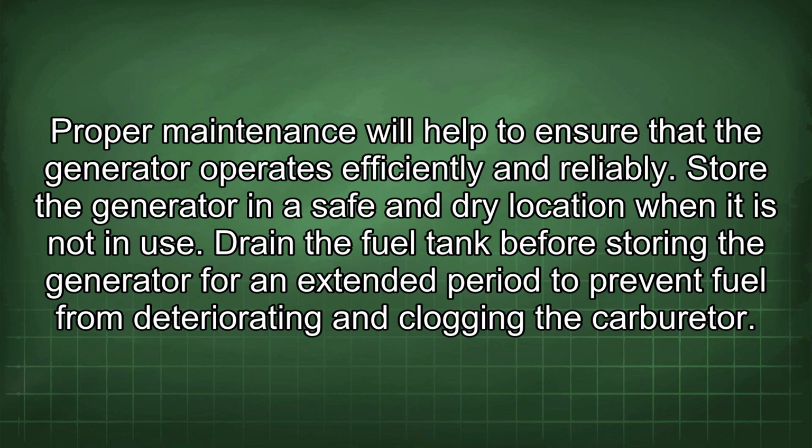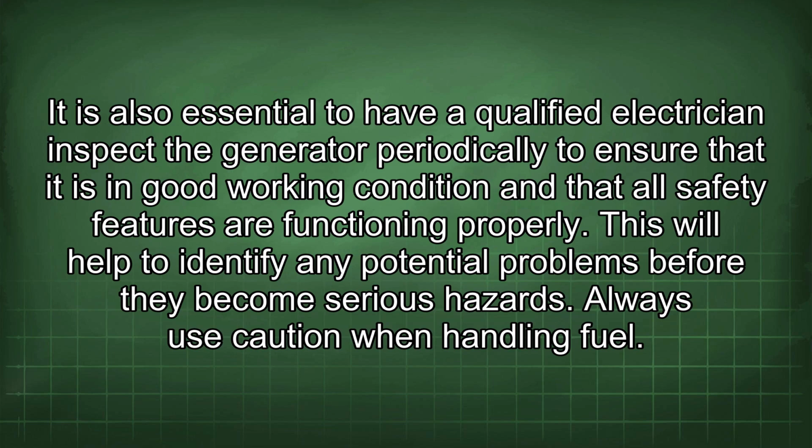Drain the fuel tank before storing the generator for an extended period to prevent fuel from deteriorating and clogging the carburetor. It is also essential to have a qualified electrician inspect the generator periodically to ensure that it is in good working condition and that all safety features are functioning properly. This will help to identify any potential problems before they become serious hazards.